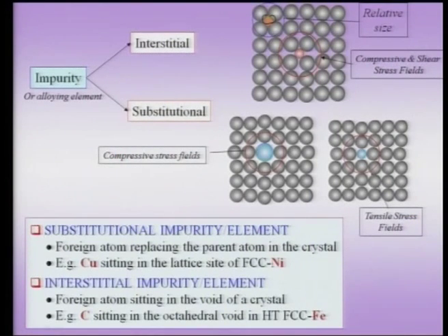And this, as we shall see later on, is a very important effect, especially when I am talking about, for instance, carbon in steel and talking about the interaction of these carbon atoms with a dislocation core. So, this would be an important thing we will consider later, and this is coming from the long range stress fields of the dislocation, which is interacting with the stress field of the interstitial atom.